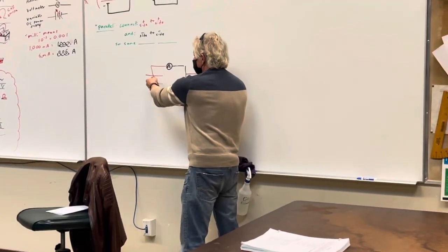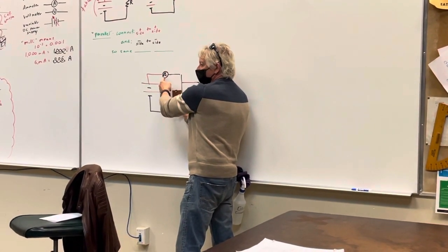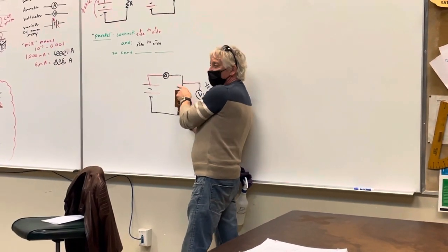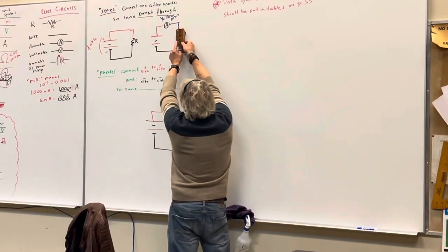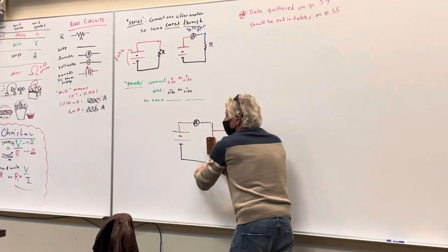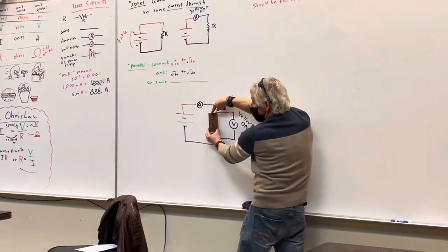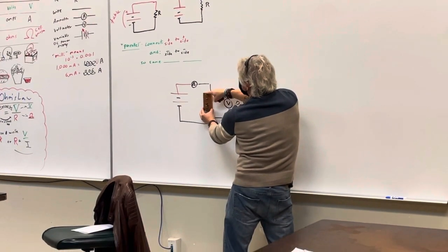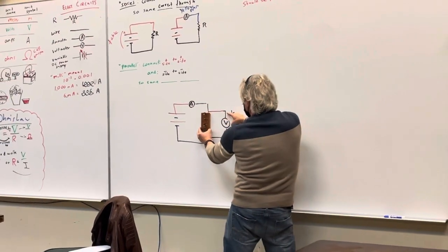I'm going to take this out of the table. I'm going to go into my yellow meter that's measuring amps. I'm going to go out of the yellow meter and connect it here. And then I'm going to go back from the other side, back to the table. Then I'm going to take my other yellow meter and connect on one side, high, and then the low. And so the drop across the resistor in voltage is the drop across the meter.